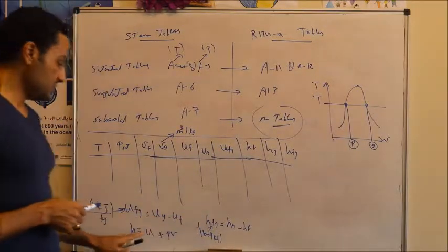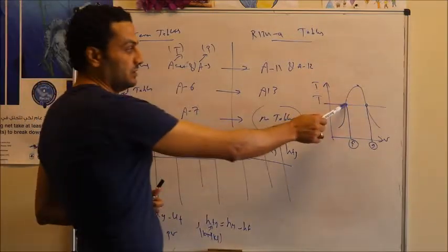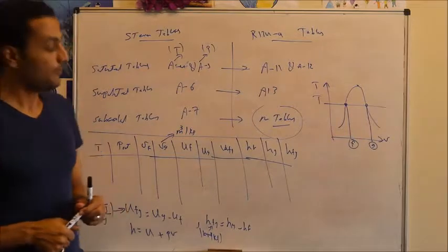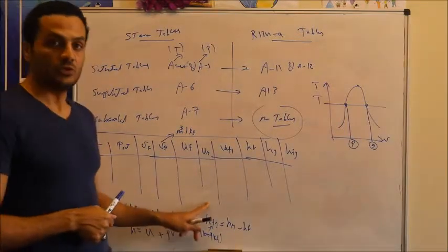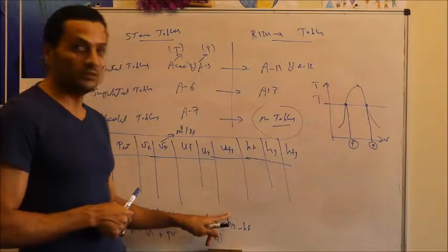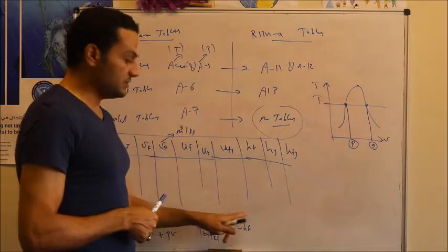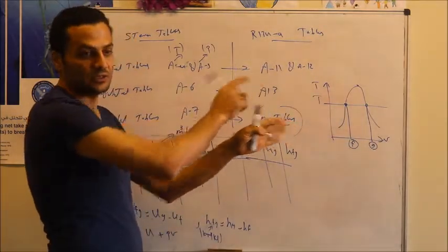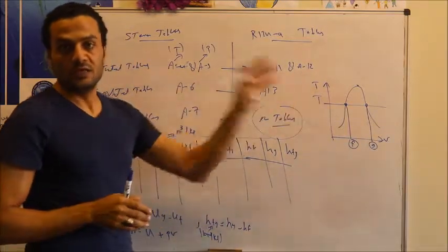h_fg represents the total energy of the flow, so from the saturated liquid to saturated vapor, h_fg is equal to the latent heat of vaporization. So h_fg is the difference between the saturated vapor enthalpy and the enthalpy of saturated fluid. This difference represents the energy that has been added to this substance to convert it from the liquid phase to the gaseous phase.